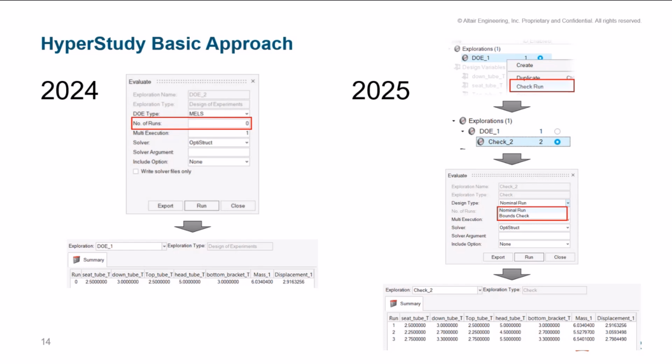Often we'll see where if you perturb a variable to its extreme bounds in one direction or another, elements can potentially get distorted, or you could have contacts or overlaps or things that will either cause the solver to fail or would be undesirable in any sense in your model. So it's a good check for that in particular.